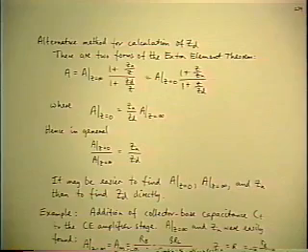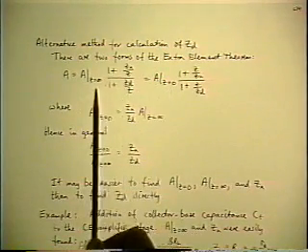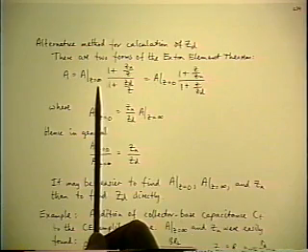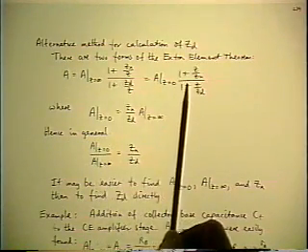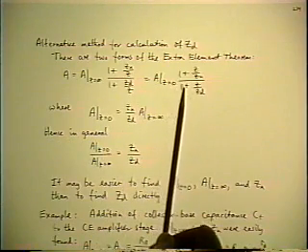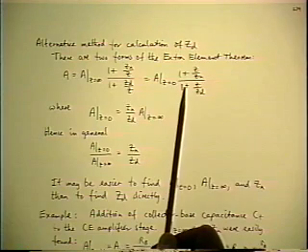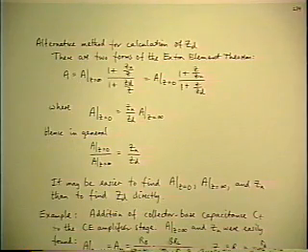There are two forms of the extra element theorem, depending on whether the reference gain that you're starting with corresponds to the element being infinite or the element being zero. They're dual forms. And we found the second version, for the series element, was obtainable in a couple of lines of algebra from the first one. In fact, this is how we did it.